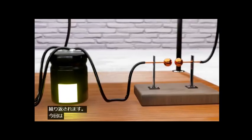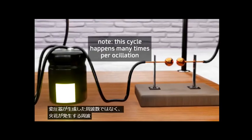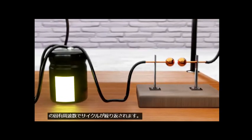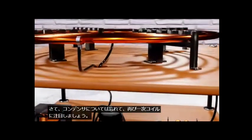This time the cycle will not be at the same frequency that the initial transformer was giving us, but rather the frequency at which sparks occur and the capacitor charges and discharges. That is, the intrinsic frequency of the resonance circuit. But now let's forget about the capacitor, and let's focus on the primary coil.